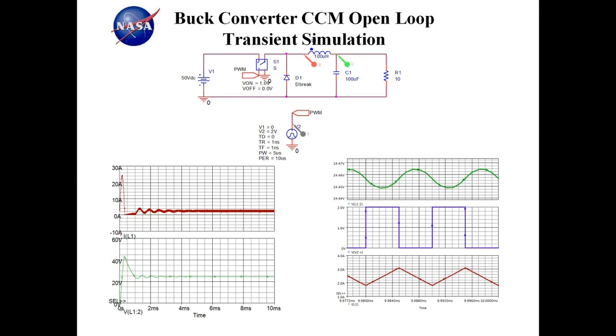If we simulate that for 10 milliseconds, we see that response, which is kind of ugly when you consider that overshoot. But again, this is a circuit that has no closed loop control, and in a subsequent series we'll close the loop on this guy and show how much we can improve that output response. So let's generate this schematic for the remaining part of our time.